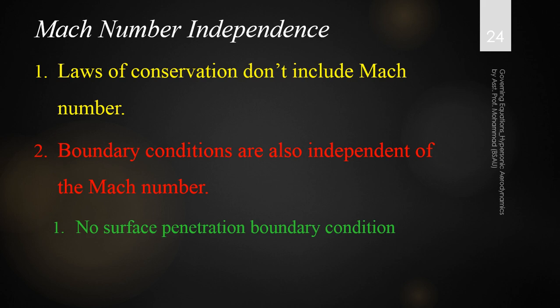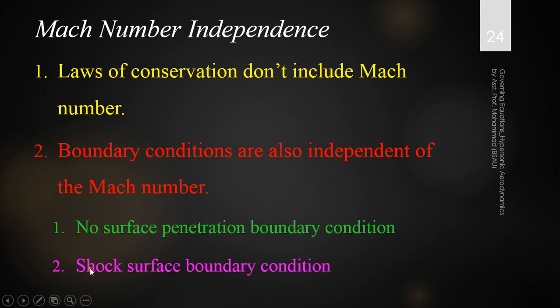Mach number is basically affecting the second, the shock surface boundary conditions. And these shock surface boundary conditions, we also saw, at very high Mach number become free from the Mach number. Yes, at the subsonic and supersonic levels they are affected, but in the hypersonic range they are not affected by the Mach number.